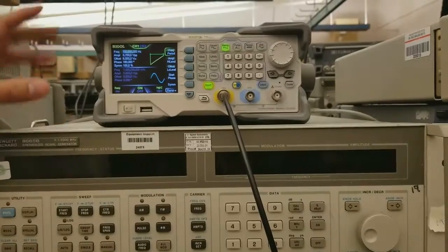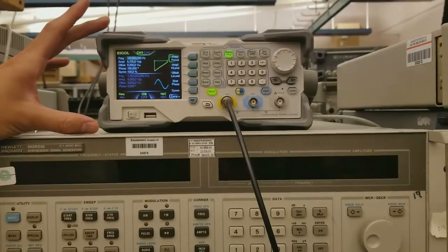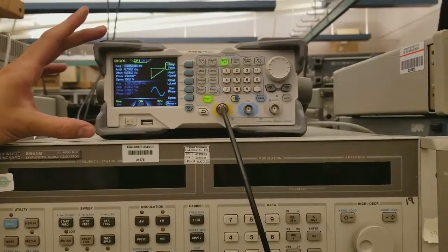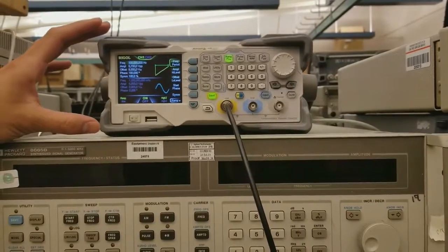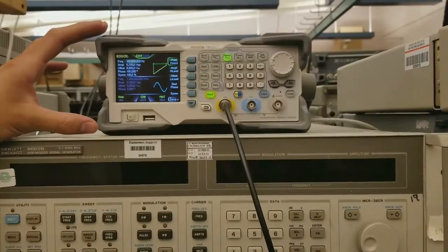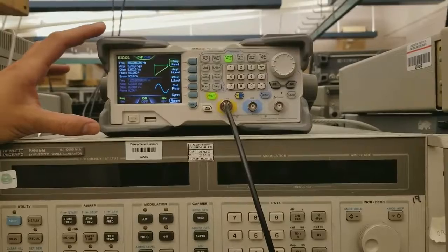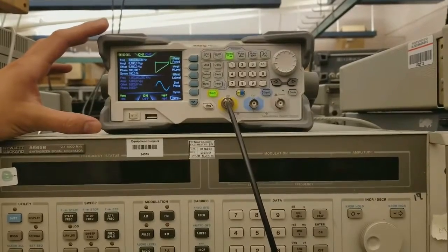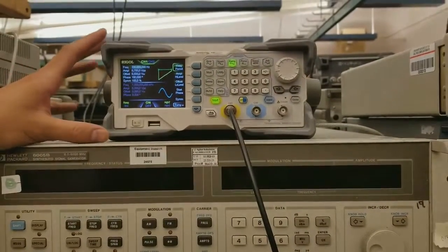So here we have our input to our voltage controlled oscillator, which is a ramp function from 6.5 volts to 6.7 volts. This will give us a frequency between 2.35 and 2.37 gigahertz, which is in the range that we want for our antennas.